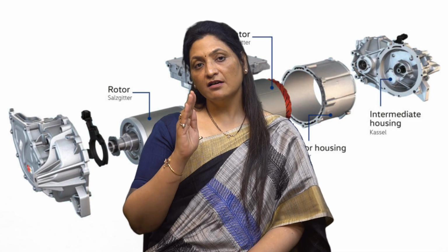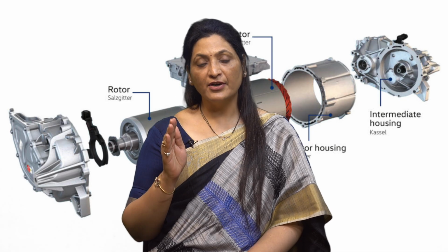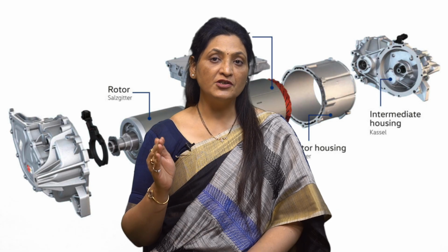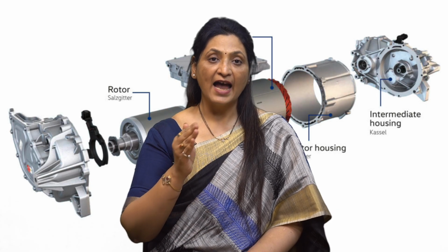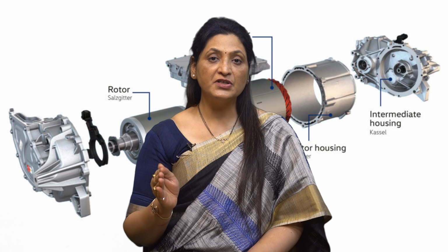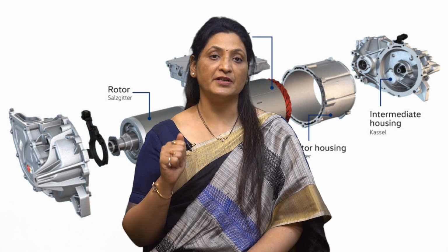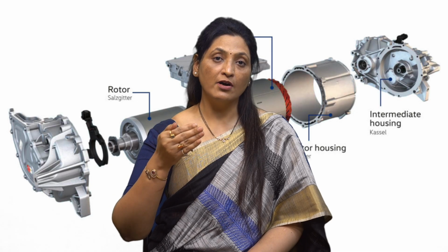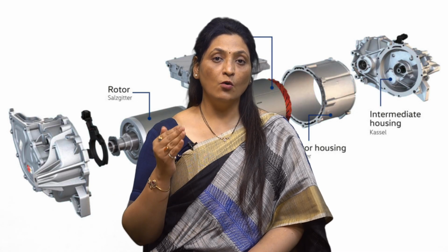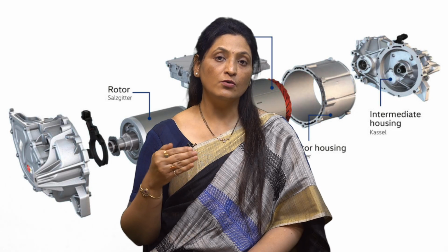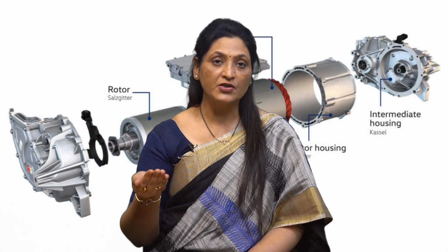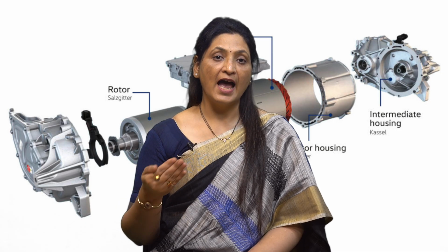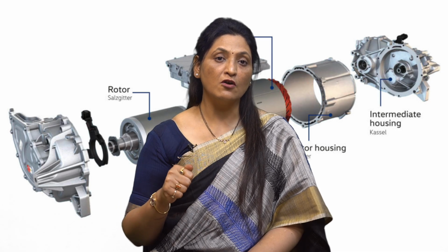Load torque is a critical factor in the operation and the performance of drive systems. Load torque is essential for motor sizing and selection, energy efficiency, control and stability. So, let us study what this load torque is. The load torque has the potential to drive under all conditions, and it always opposes the motion, and its sign changes on reversal of motion.